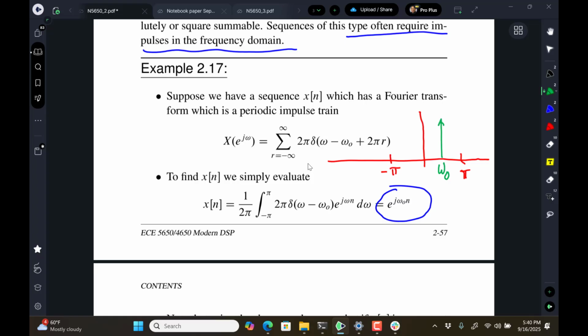So to be able to take the DTFT of this one, we would have to truncate outside of negative pi to pi? Well, to take the DTFT of this one, we just have to say it's this. We just have to kind of wave our hand. It's called the Fourier transform in the limit, to say that we can get it as a delta function. And then we have that nasty little delta function sitting in there, which is not mathematically manageable in the same sense.